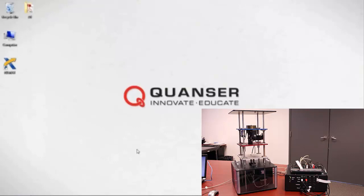So a little bit more about the hardware. Right here we have an encoder installed that we can use to measure how much our car model is deflected from the base of the unit. Back in the end there's a black box, our accelerometer, that we're going to use to design an observer later in this presentation. And right in the center there's a motor that we use to dampen the effect when the active suspension hits an obstacle.